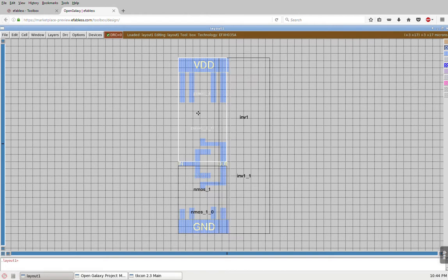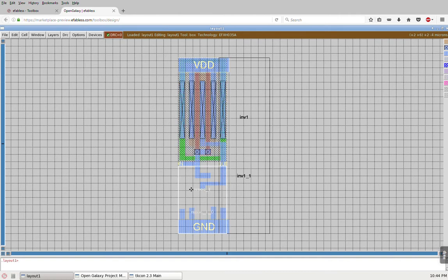I can select again individual transistor. In this case, there's a PMOS device over here, and over here, after selecting and using the / I can actually see what the entire cell is made of. So there's a PMOS device over here, there's an NMOS device. Magic differs from standard layout GDS2 based layout tool in that a lot of the things that you're seeing are actually abstracted view, which makes things fairly easy to look at.